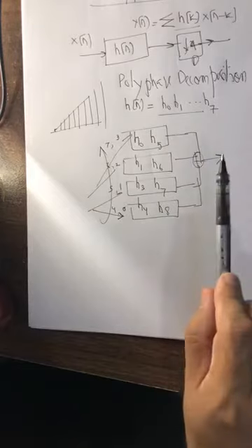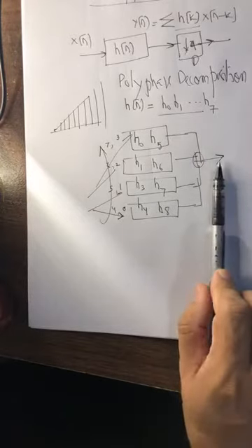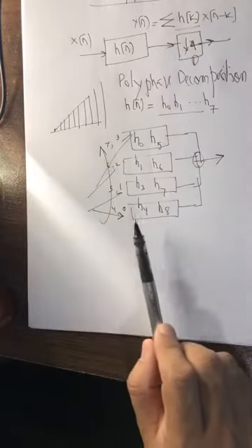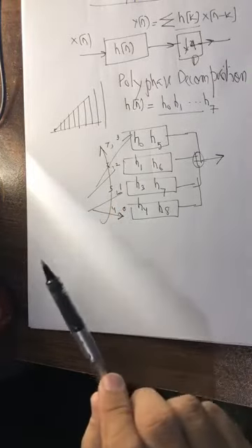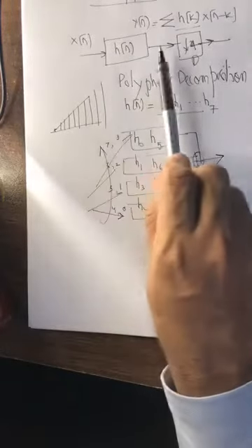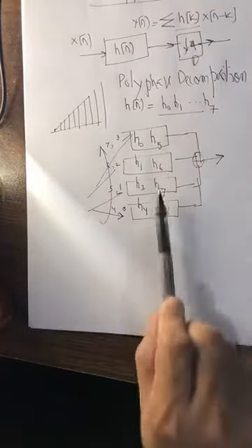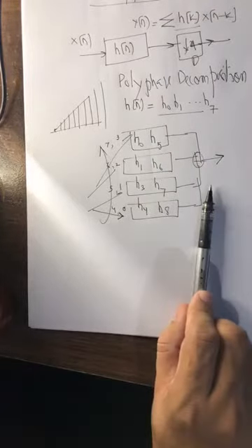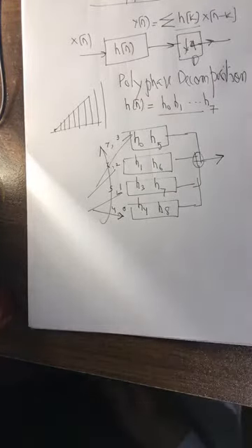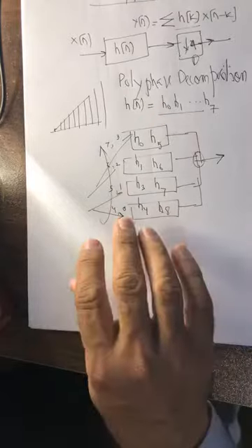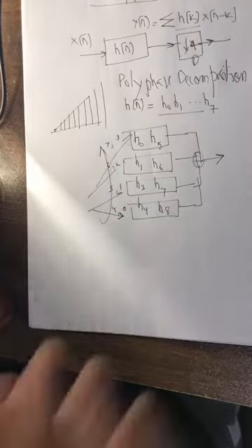So this is how you only compute what is required to be computed, and this is mathematically equivalent. We will not get into the mathematical proof of this, but it is equivalent to passing a signal through a filter and then throwing away samples. Both are equivalent, but here you are not throwing away samples. For every 4 samples you are computing 1 sample. So perhaps in the next class we will do an example on this so that you understand. We'll actually do this in MATLAB.